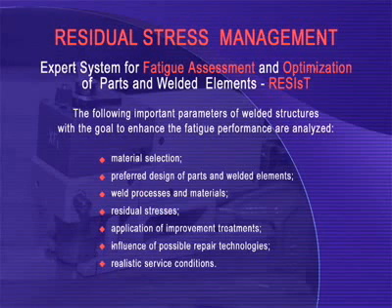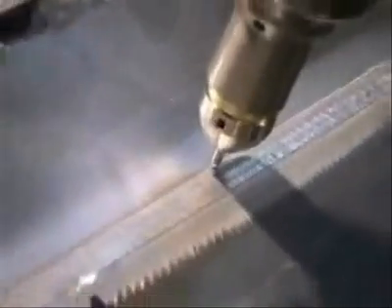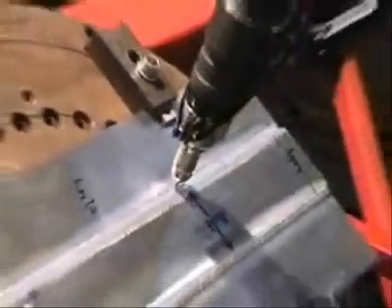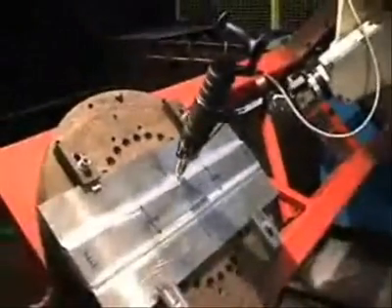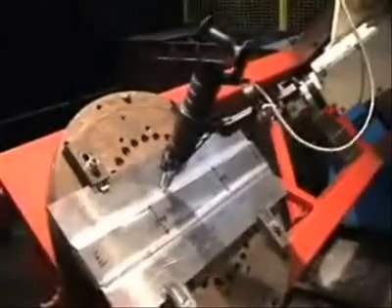Material selection. Preferred design of welded elements. Weld processes and materials. Residual stresses. Application of improvement treatments. Influence of possible repair technologies. Realistic service conditions. Ultrasonic peening is the most effective and economical technique for beneficial redistribution of residual stresses and fatigue life improvement.